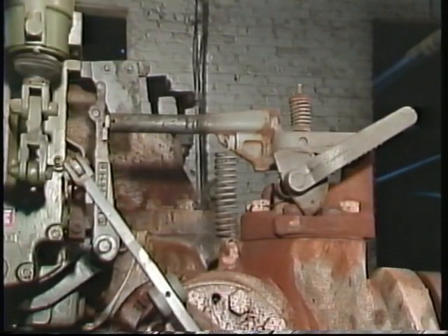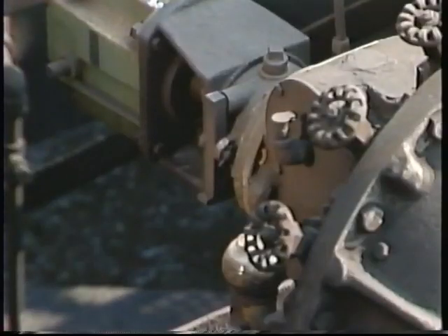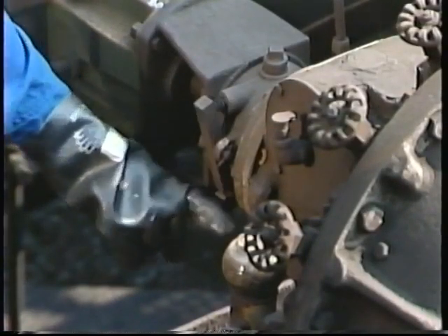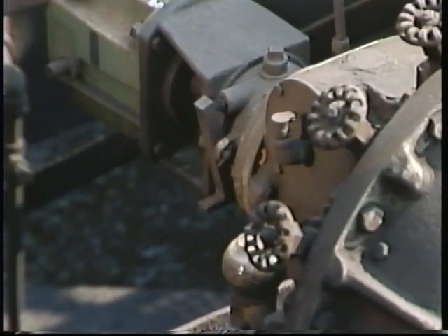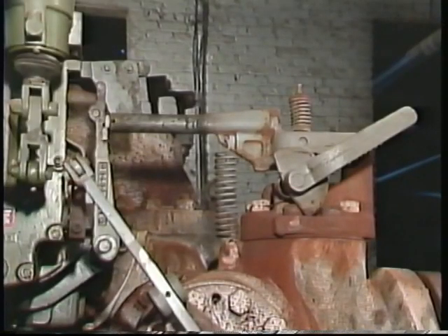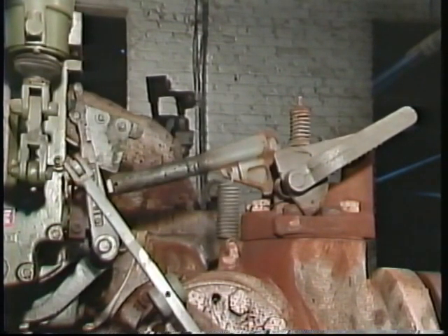Generally, if speed goes beyond a certain limit, a trip valve in the overspeed trip mechanism automatically closes to stop the turbine. There are a variety of arrangements for overspeed trip mechanisms, but they all operate on pretty much the same principle. Basically, if the turbine overspeeds, the shaft's centrifugal force will cause the trip valve in the overspeed trip mechanism to slam shut. When this valve shuts, it cuts off steam to the steam chest and stops the turbine.